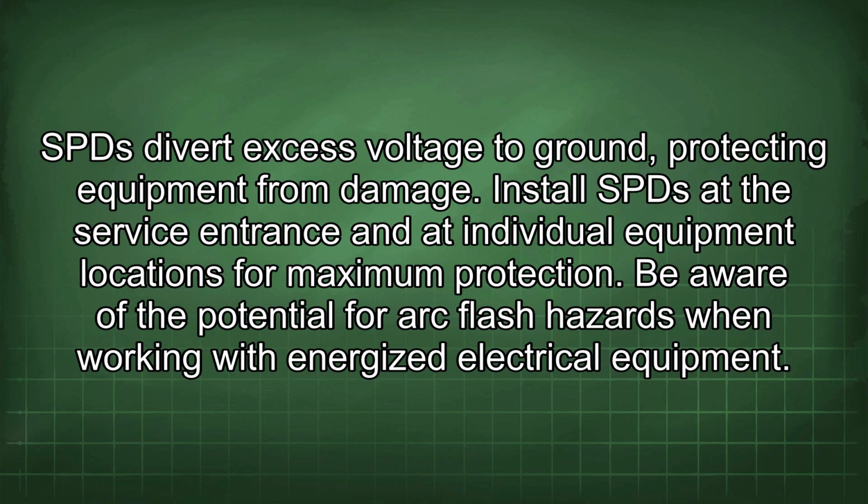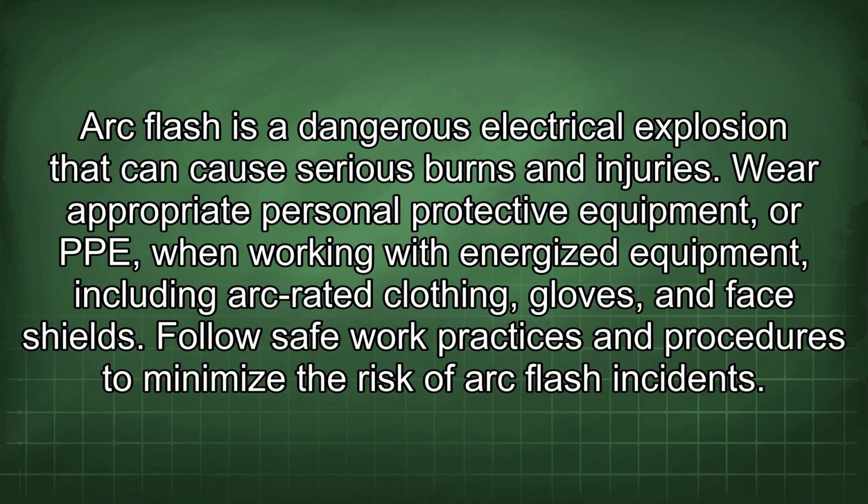Be aware of the potential for arc flash hazards when working with energized electrical equipment. Arc flash is a dangerous electrical explosion that can cause serious burns and injuries. Wear appropriate personal protective equipment, or PPE, when working with energized equipment, including arc-rated clothing, gloves, and face shields. Follow safe work practices and procedures to minimize the risk of arc flash incidents.